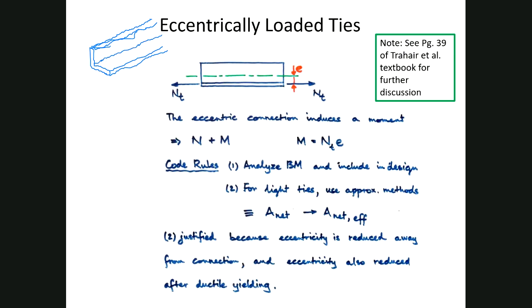If we put the hole for connecting it along the bottom, we're going to put a bolt in there, connected to, let's say, a plate that's coming out here. That plate is welded onto something else, or connected onto something. Say there's another hole there, and another angle section connected onto that, so they're connected together.